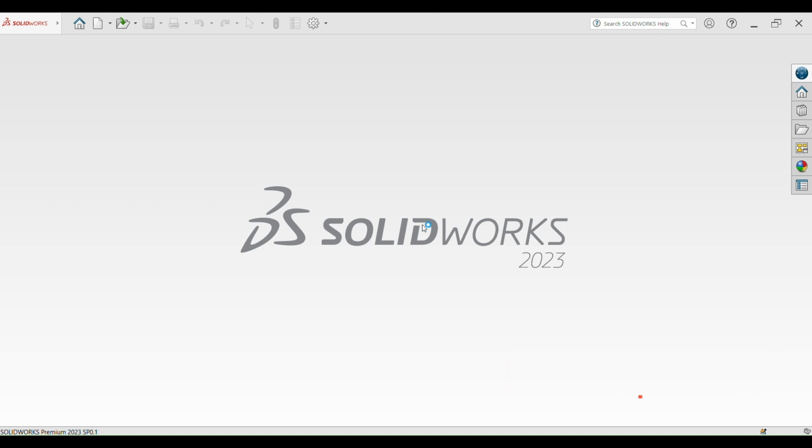As always, we are going to be implementing many of the SolidWorks tools, such as the extruded boss base and extruded cut features. We're also going to be implementing many of the SolidWorks sketching tools. However, in this video, we are going to be learning a new SolidWorks feature called the swept cut feature. You can think of the swept cut feature as a more advanced version of the standard extrude cut feature that we've used in our previous videos. So without further ado, let's get started.